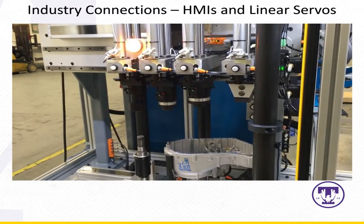So that movement that you just saw where this slide went from here to here was performed by this linear actuator. So this box that you see with the shiny stripe on top, that actually continues all the way over to here, and that has what's called a ball screw inside. And that screw turns and moves this sled back and forth, and that screw is driven by a linear servo, or in this particular situation, a linear stepper motor.